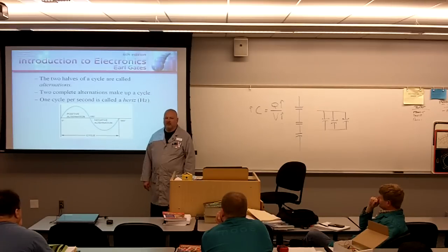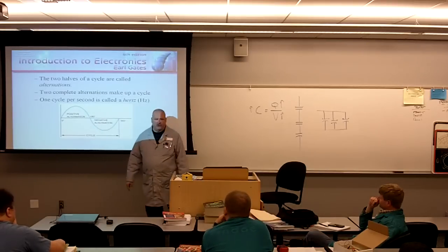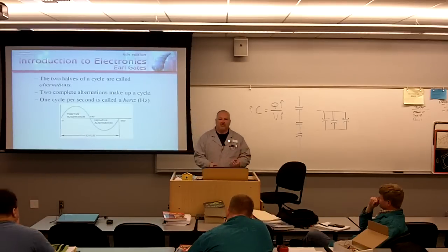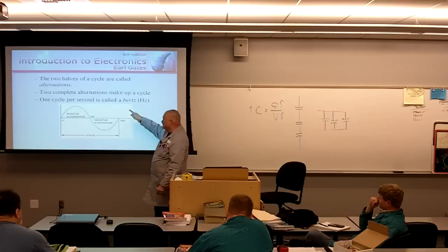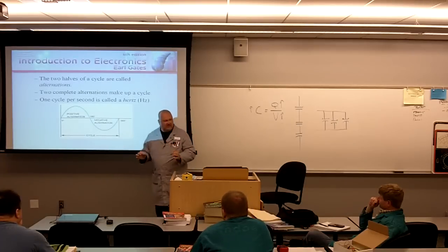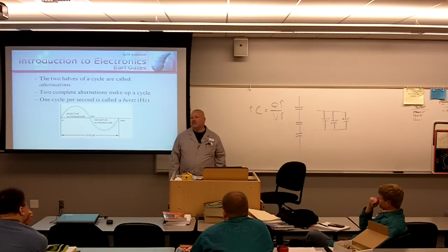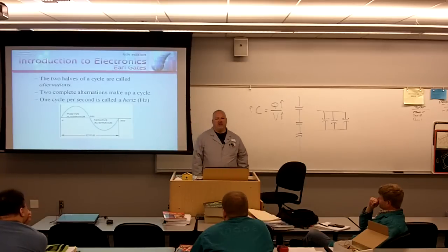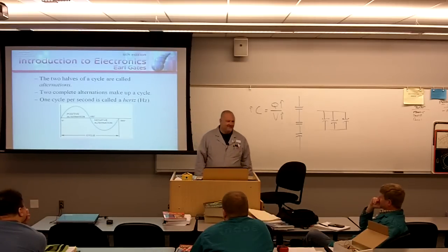Did any of you realize this prior to this lecture? Kind of cool, ain't it? With the sine key in the calculator, you could predict any voltage present along the wave, what's called an instantaneous voltage. Meaning we're taking a sine wave, stopping it at a specific instant and saying what voltage is present. Remember that. That's a powerful tool for you. And by doing that, you're doing trigonometry. But shh, keep it a secret.